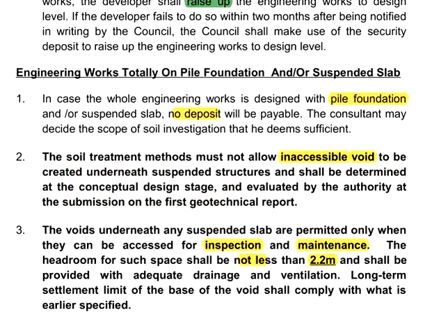That means that when you are using the suspended slab system together with the pile foundations, this can prevent the infrastructures from undergoing settlement. However, this cannot prevent the soil from settling. Ultimately, there may be voids underneath the suspended slab system. Now, it is important to ensure the voids shall be accessible or open. The guideline did not provide any explanation regarding why it is so.